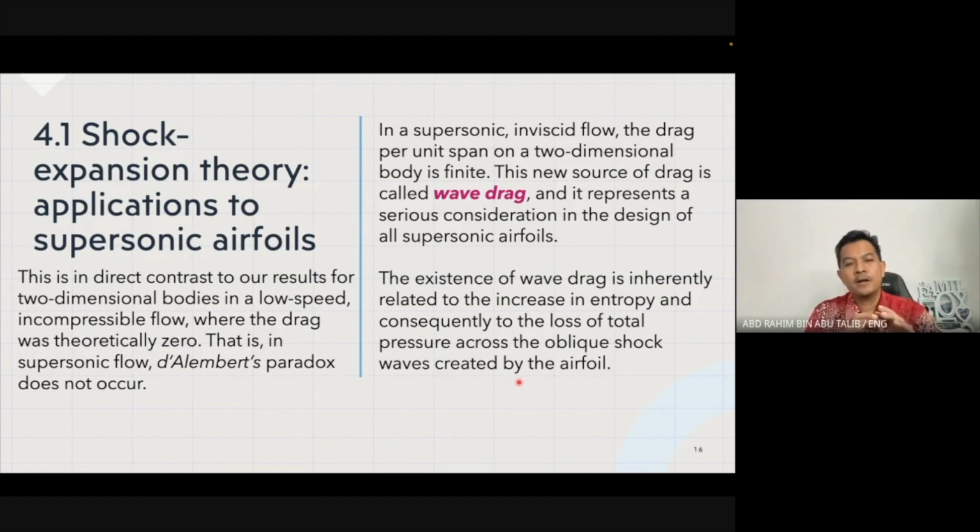When you look into a scenario, you have to determine whether at the leading edge it is going to have an oblique shock or an expansion wave, and that determines how you find the values of P2 and P3 respectively using the appropriate formulas.